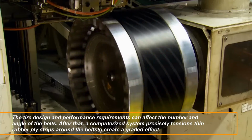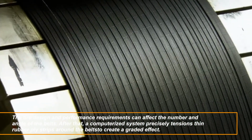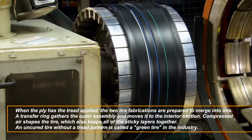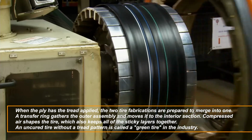After that, a computerized system precisely tensions thin rubber ply strips around the belts to create a graded effect. When the ply has the tread applied, the two fabrications are prepared to merge into one. A transfer ring gathers the outer assembly and moves it to the interior section.